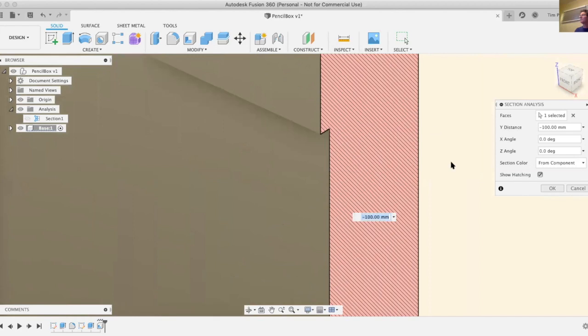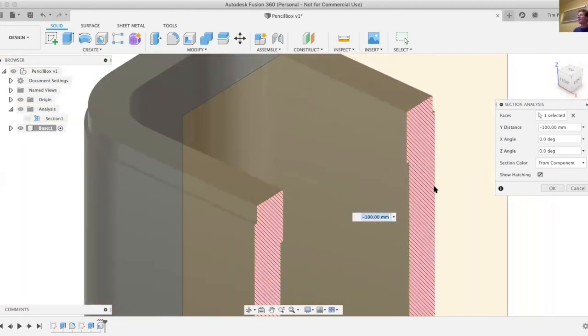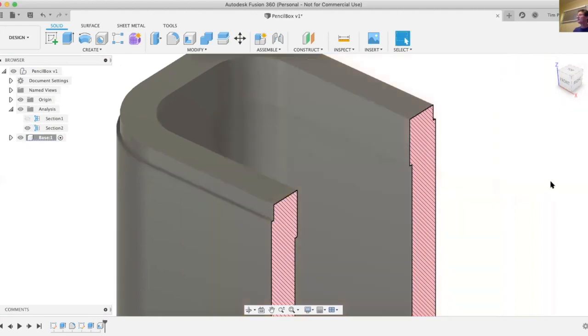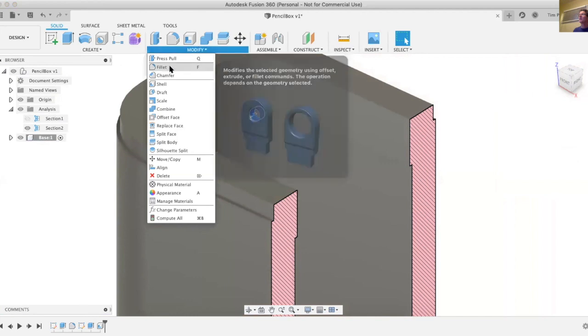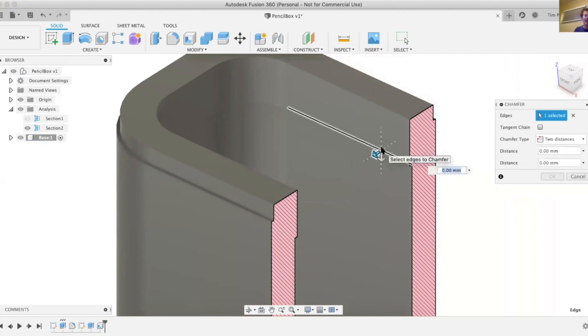The chained ones. Oh, yeah. Okay, yeah. So basically, what that was saying is, let me go back to the modify chamfer, and so tangent chain. So if tangent chain is not selected, if I pick an edge, I'm only going to get the edge I actually pick.